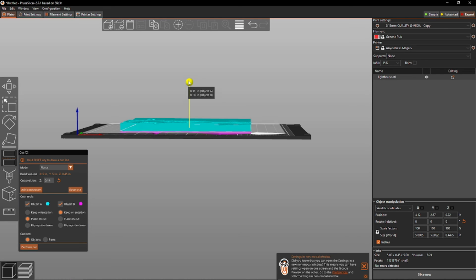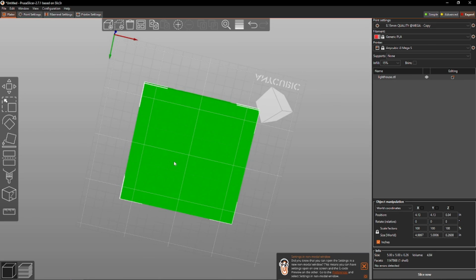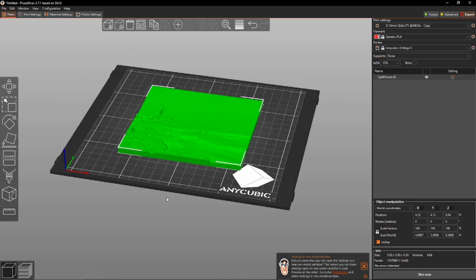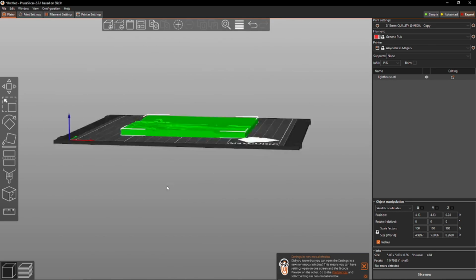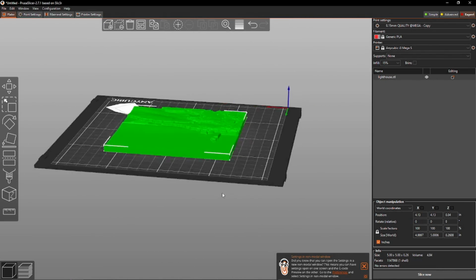And what I usually do is just slice a little bit off the back of it. That's why I make it extra thick. Go over here and uncheck B and hit perform cut. And what that will do is that will slice that back so it's nice and even. And the way that you can see that is just, if you're using your left mouse button, you can do your orbit type thing.